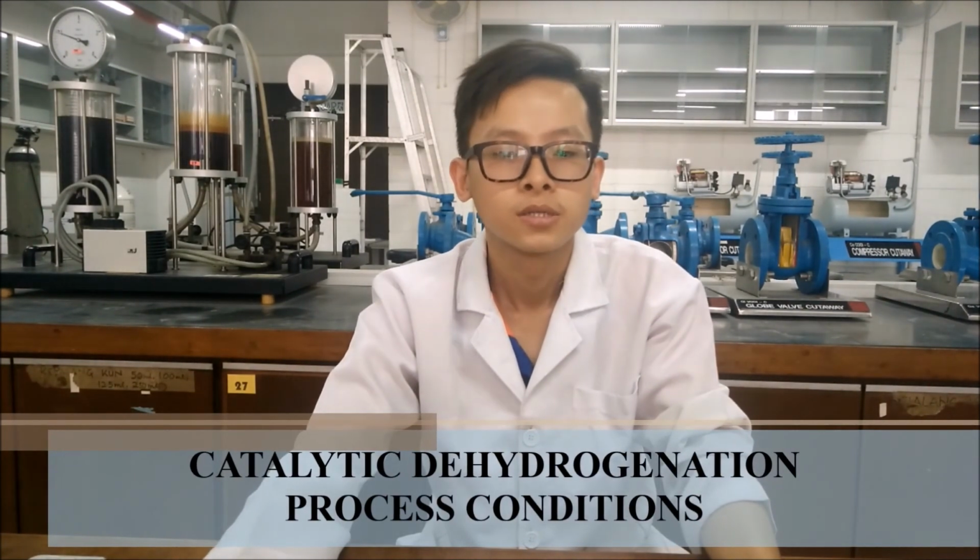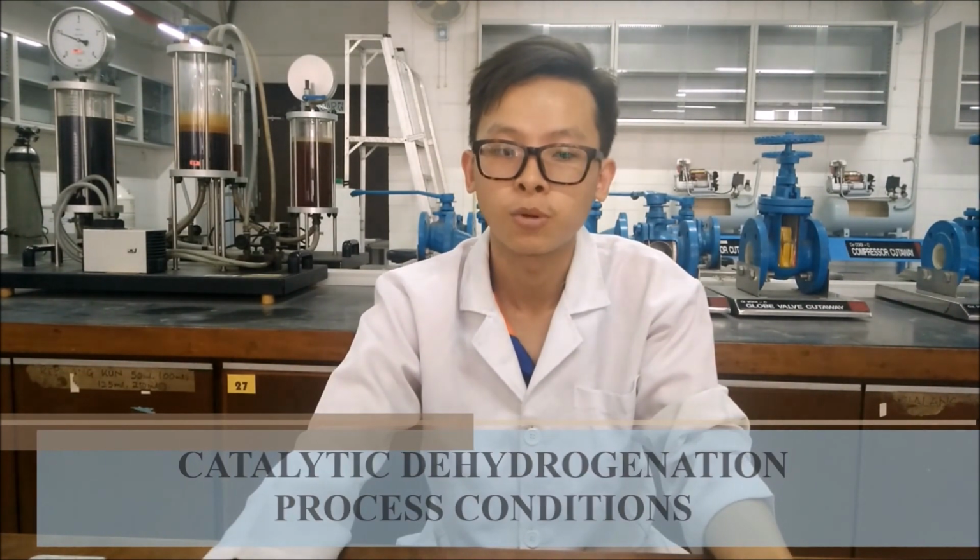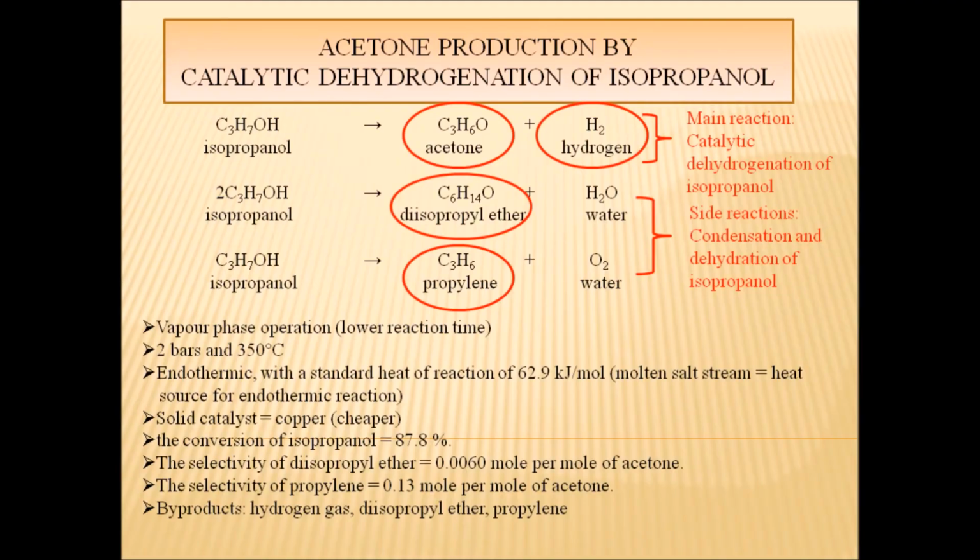In our plant, the catalytic dehydrogenation of isopropanol takes place where two side reactions will occur simultaneously, which are a condensation reaction of isopropanol to diisopropyl ether and a dehydration reaction of isopropanol to propylene. The reaction takes place at a temperature of 350 degrees Celsius and a pressure of 2 bars.